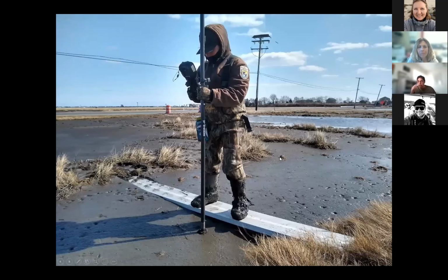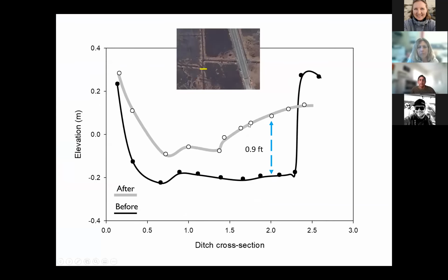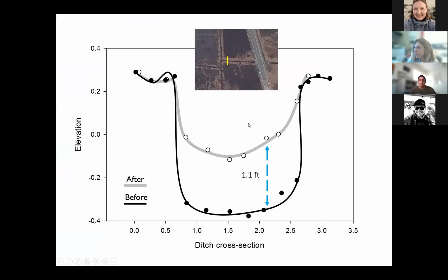Then, beyond the plate where we wanted the material to go, it did go into some of the ditches that weren't planned to be filled, which act as a kind of conduit for water through the culverts. So we did some measurements of those just to see how they change over time. If you see here, this is one of the main culverts and how water gets into the site, and this is an example of measurements around here. There was significant accumulation of material in these ditches, which affects the flooding regime in the project area.